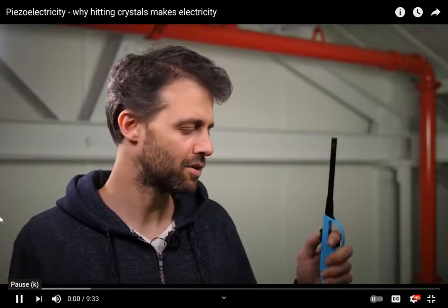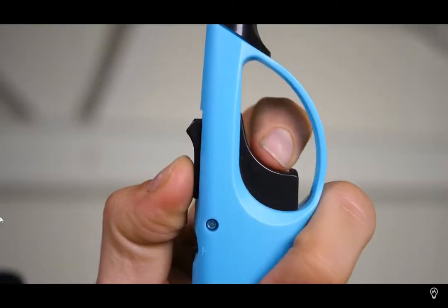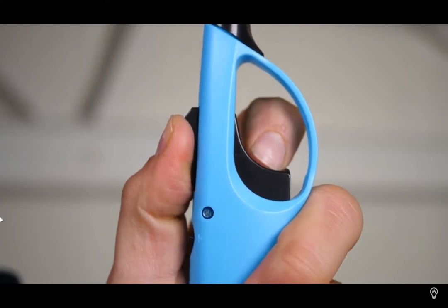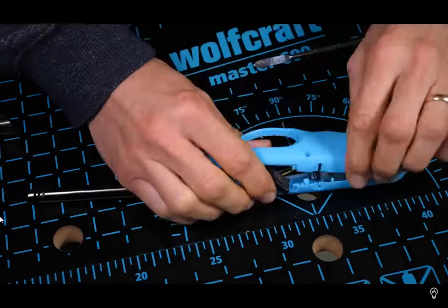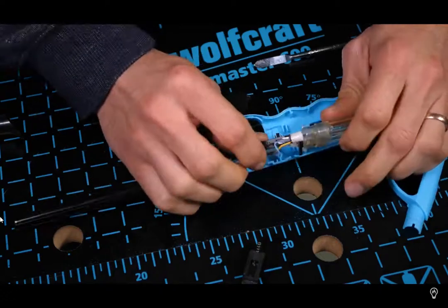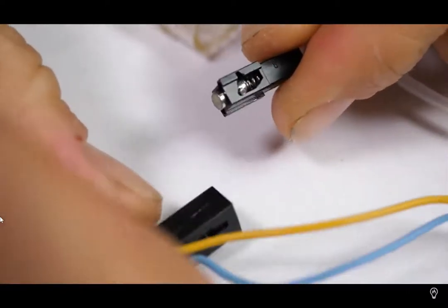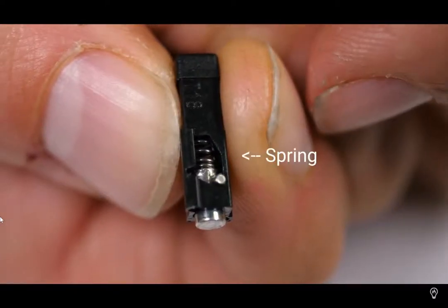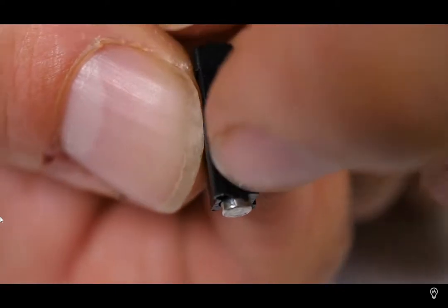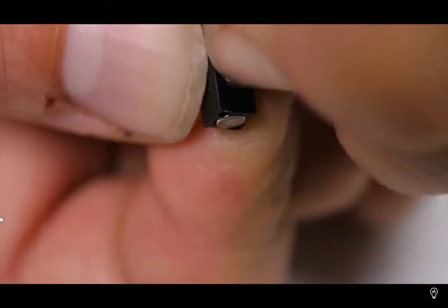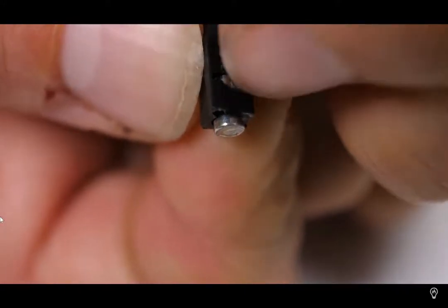When you press down on the trigger of a barbecue lighter, you'll notice it's quite hard work. Like, it's not like pressing the button on a remote control. You actually have to put some effort into it. Hold on. And there's a reason for that. When you press down on the trigger, you're working against quite a stiff spring, so all the work you do is stored as potential energy in the compressed spring. And in front of that spring is a tiny hammer, so that when the mechanism finally gives way and the spring is released, all that potential energy stored in the spring is turned into kinetic energy in the hammer.